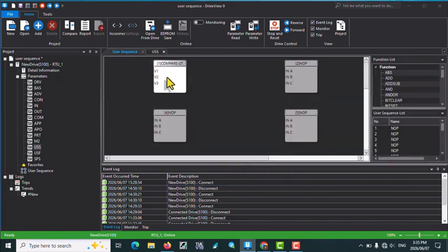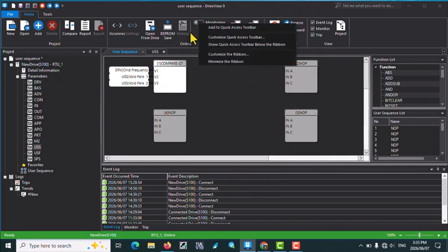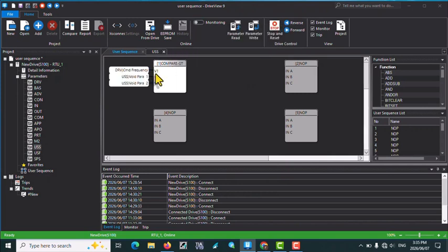Alright, now for function 1, I click on the monitoring option. Then I exit monitoring again. You can see that its first input is DRV0, which is my command frequency. The second input is user parameter 1, which has a value of 5. My third input is also user parameter 2, which has a value of 2. So if my A is greater than B, the output will be set to the value 2, which is my output. The address is 6 hex.